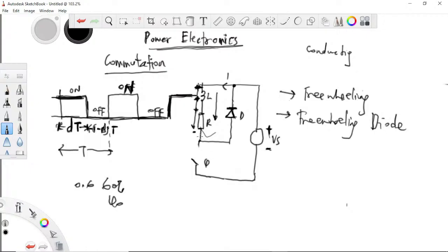So in the on state, reverse bias, current flows through here, right? In the off state, the inductor will reverse polarities and will now start supplying current through this branch, which will go through the diode. The diode now becomes conducting, right? So now, the current in the inductor rises up to a certain level in the on state, then in the off state, it will supply current.